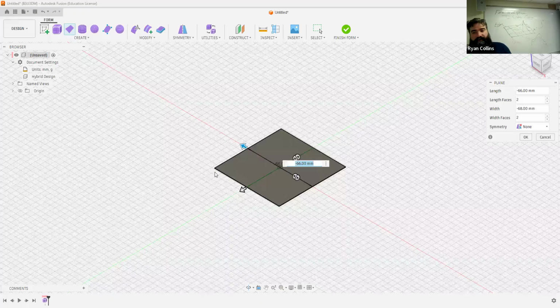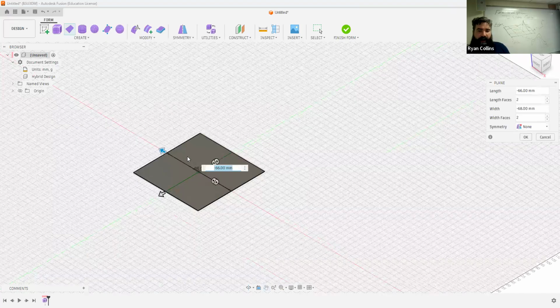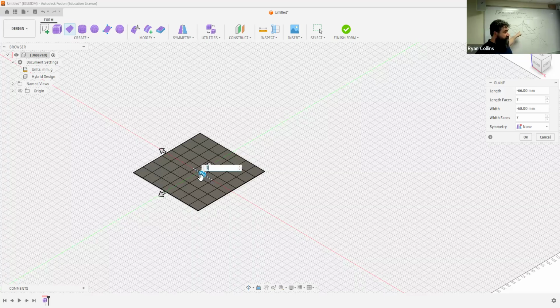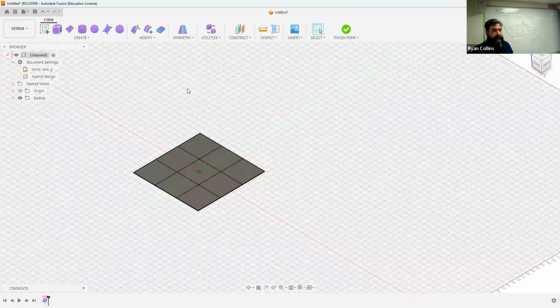Don't hit enter. When you click that in, now you have a face. I can add faces in one direction with these sliders, and I can add and subtract faces in the other. This is what I mean by, I got all of these here. Keep it simple, and you can work a little more easily. Let's keep it at like 3 and 3, something like that. That'll work easily. Now, we have symmetry, and that's something you can play with later, but I'm not going to worry about that right now. I hit OK. The main other tool we're going to be working with in this project,